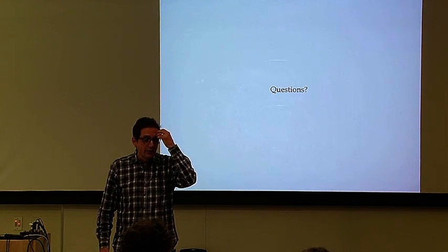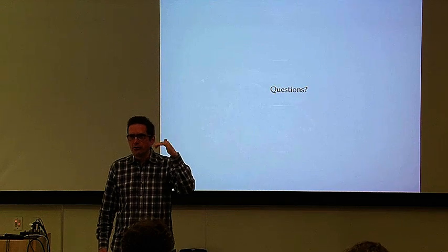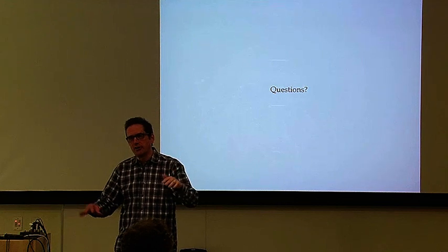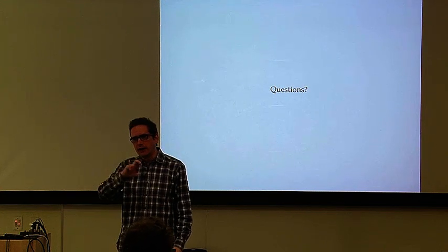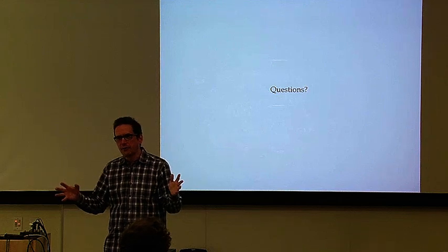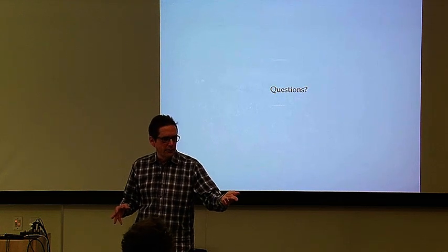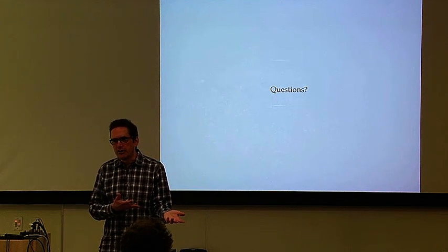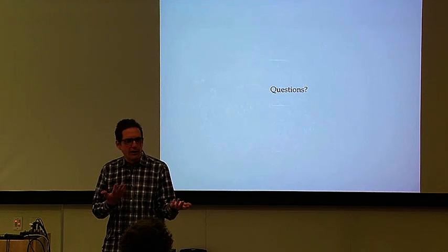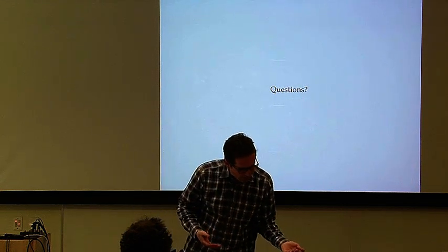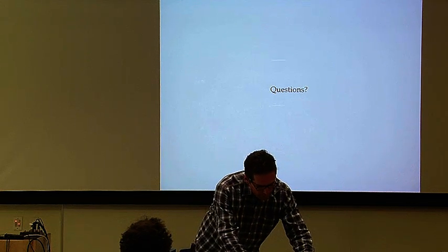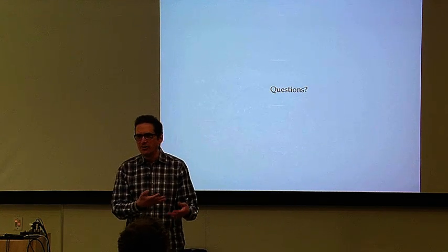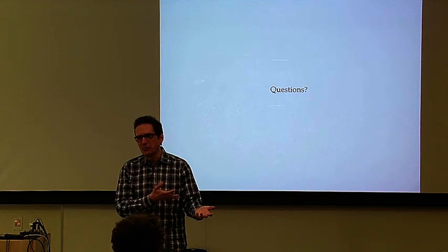Yeah, one thing is that playing with different saturation algorithms has a big effect. If you model an arctan saturation or you model x minus x squared over 6, these all have different sounds. I started with the cheapest saturation algorithm, and I really liked it. It got sort of aggressive and noisy. The other thing you find is that the sounds you would put into this are different from my percussion tracks, so you start tuning the algorithm to suit those sounds.